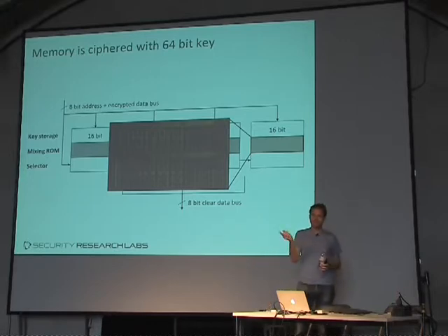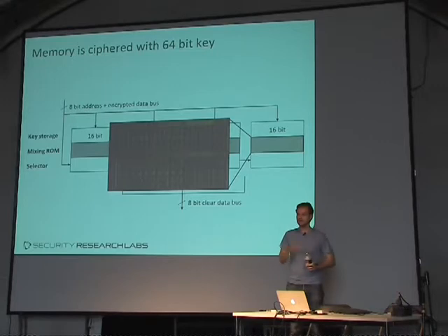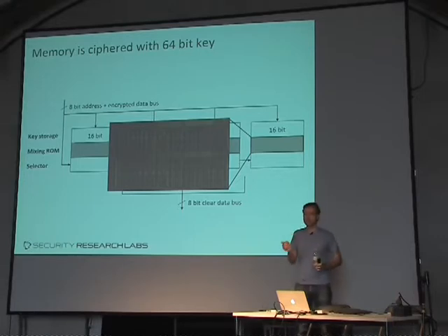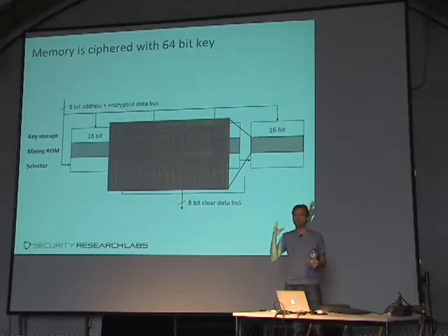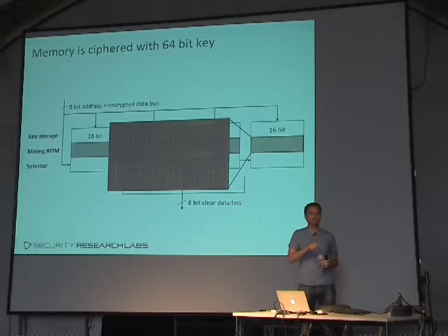It's kind of to prevent exactly what we are doing now: reverse engineer it once and then make this work on all the chips of this line. However, the way they differ is by putting in another ROM and changing that ROM, and we already know how to optically read out ROMs, so this is just one more variable to fill in during the analysis. This is nothing that would make the readout of ROM any more complicated.